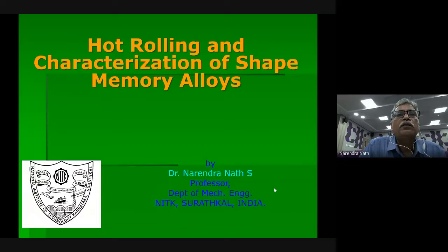Today's afternoon talk is hot rolling and characterization of shape memory alloys. And why hot rolling? Normally, with these shape memory alloys, if it is titanium nickel based, when we want to give any new shape, for example a rod or a plate, cold rolling is not a solution. When you cold roll it, it will crack automatically, and once it cracks, it is not possible to use it. That's why people are going for hot rolling. And whatever little work we carried out in hot rolling, I am going to present in front of you, all delegates.